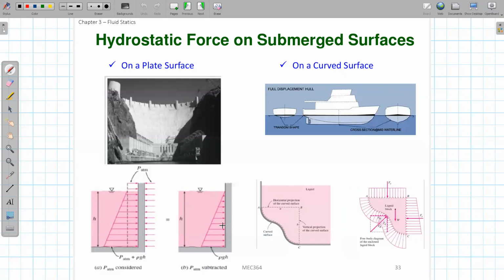They are all normal, in the inverse normal direction of the surface, and because the normal direction of the surface does not change, the pressure force direction also does not change. On curved surfaces, the story is different. At each local point on the surface, the pressure force will also be in the reverse normal direction of the surface at that point,